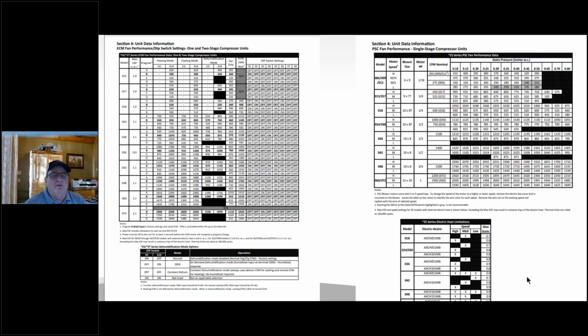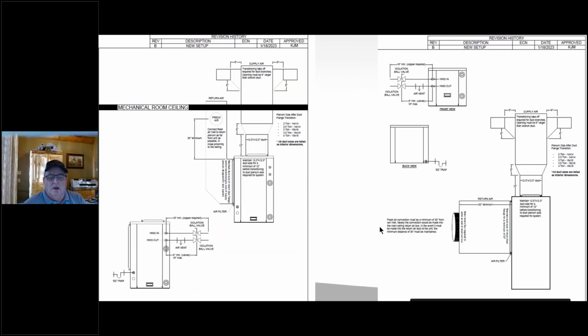So have a couple of diagrams that were drawn up on some ductwork systems. To give you a couple of examples, I wanted to talk about starting collars. Okay, this particular appliance piece here is called an offset starting collar. Notice how it has a larger intake as it is going out to the trunk line, and I'll show you some of the reasons why this is important in a minute.